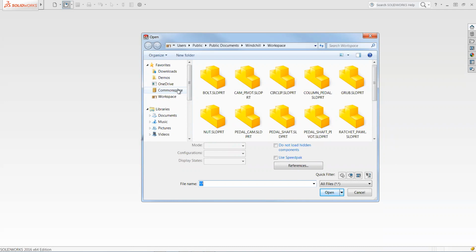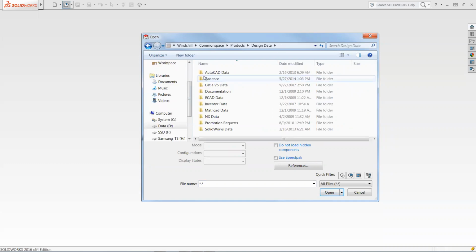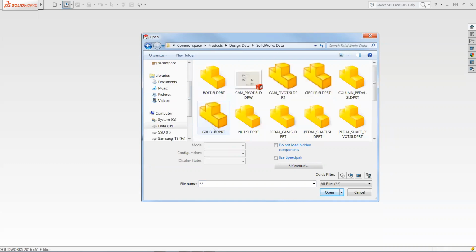And what a lot of people do is even that marked up version that I created, as soon as it's saved to Windchill, that might actually kick off a workflow that you have set up ahead of time and is automated. So once I submit that annotated version from Creo View, it kicks off a workflow. So now the designer who's going to be making the change immediately and automatically knows, hey, I need to make a change to this model. It's a task that they'll be assigned automatically. So they'll know first and foremost, as soon as they log into Windchill, what needs to be done.